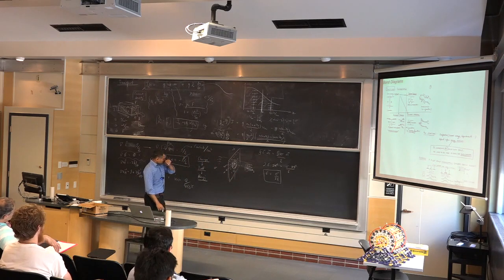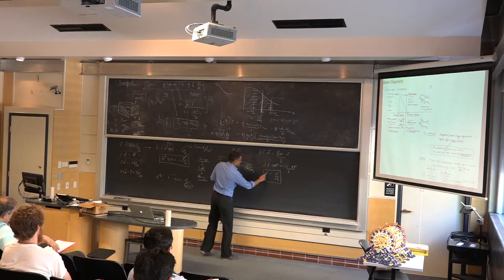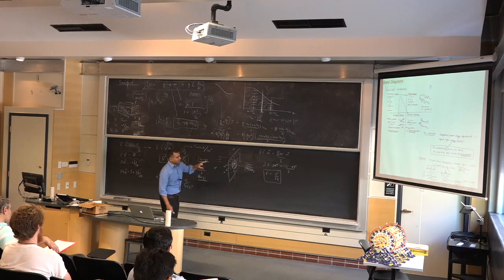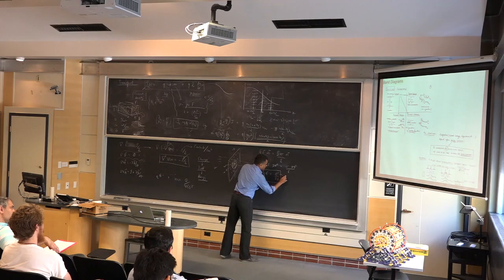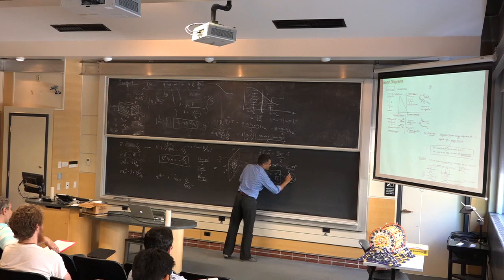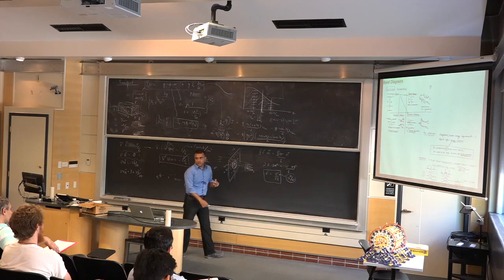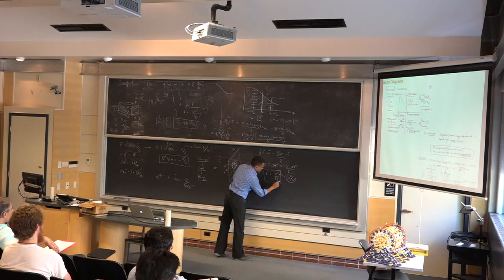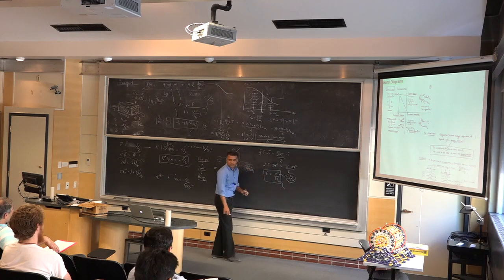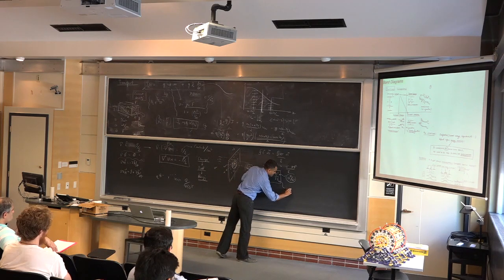And the other thing is it's useful to have a magnitude of this. So let's look at a magnitude. Just for memory, I would say that if you had a sheet charge of the order of 10 to the power 13 per centimeter square, these are numbers that will appear many times in semiconductor devices, PN junctions, MOSFETs. And the dielectric constant typically in a semiconductor is about 10, 9, depends on what we are talking about, is 10 times epsilon naught.